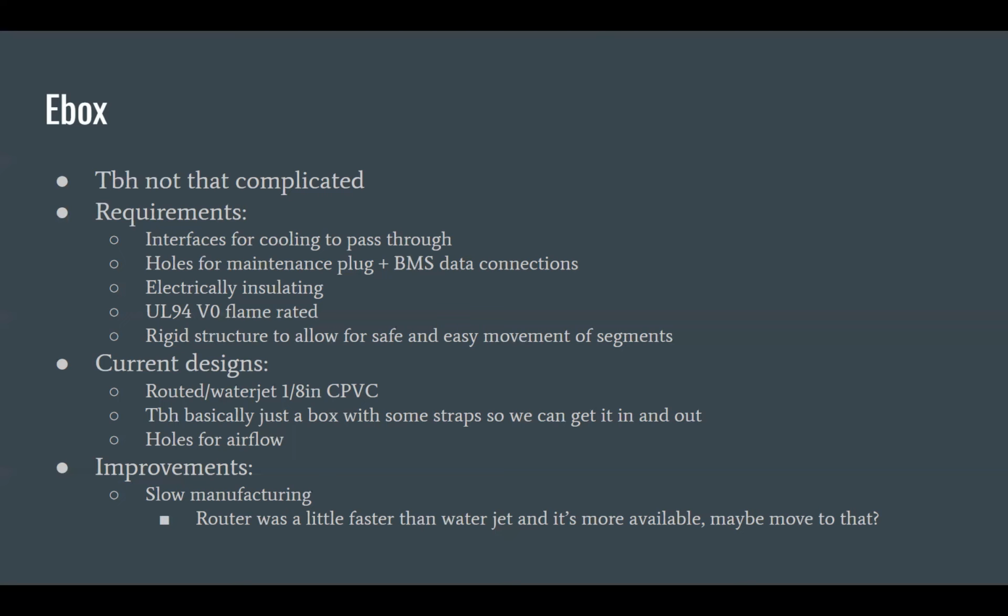And yeah, anything that's going to be UL 94 V0 flame rated, anything that meets our flammability rating, other than steel, is usually already in the range of 1/8 of an inch to 1/4 of an inch thick. And so at that point, your voltage rating is already into hundreds of thousands of volts usually. I think this polycarbonate has a voltage breakdown of like 50,000 volts or something. So obviously we don't get anywhere near that. Meaning it's 50,000. So I could put like 40,000 volts across this. I don't do that.